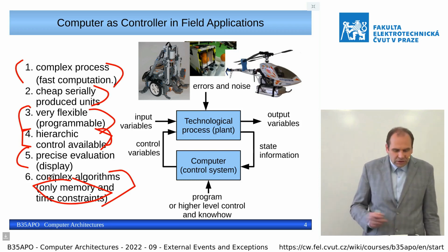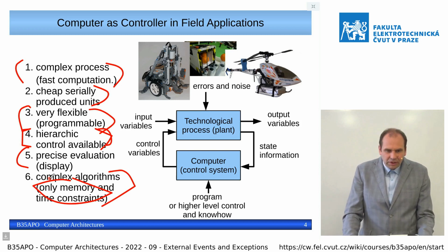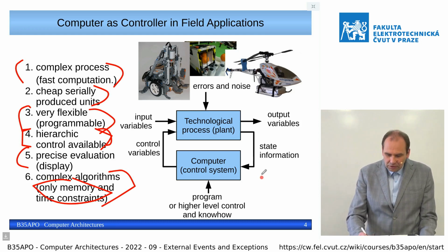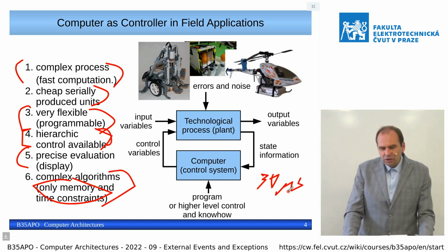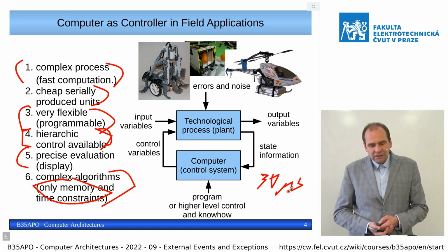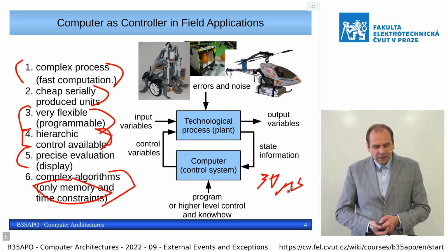On a standard x86 computer, if you are lucky and do not have a buggy BIOS and other motherboard problems, you can get maximum measured latencies of about 30 microseconds. So we have done control at 30 kilohertz on a regular PC with Linux and MATLAB Simulink generated code.